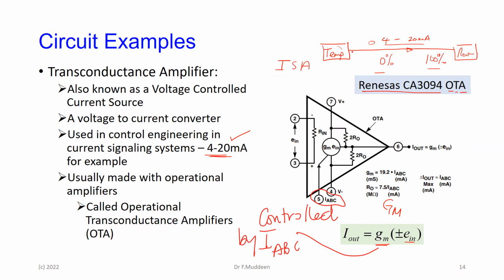Okay, let me give you a hint. If I'm sending a current here and the wire breaks, what happens to the current? The control room sees what? If you're sending some current, whatever the value is, the control room sees 0. So if I have 0 as 0%, I really don't know if there's a broken wire or if the system is actually sending 0 amps. So you need to signal in such a way that you could also detect 0 when nothing is happening. Right? So that's the answer, yes, Krista.